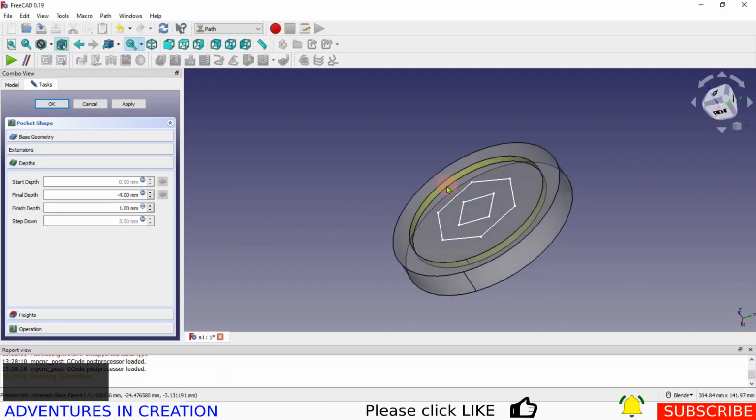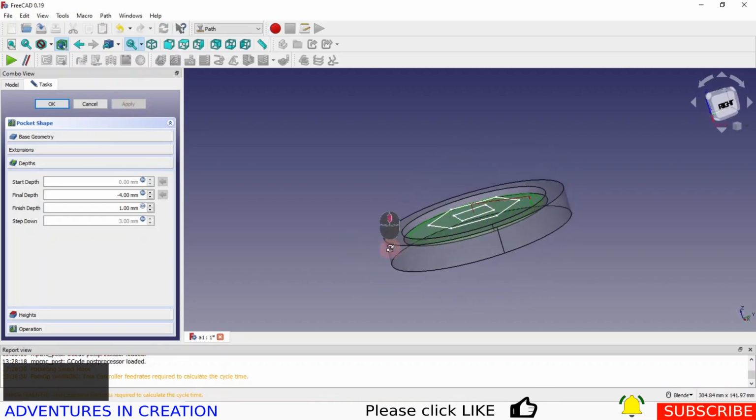So it should do 1 step down, cut that surface, and it's going to leave 1 mil for a finished depth, or cut a 1 mil cut and finish up that surface, so we'll get a decent finish on the surface. That's basically it. I can apply that now, and as you can see, there's my cutting paths.